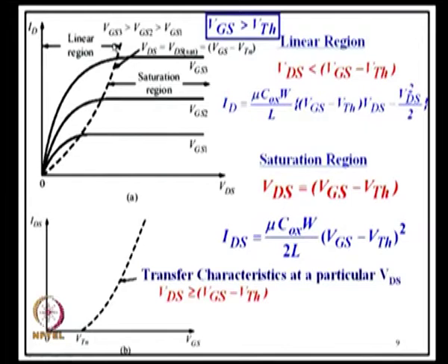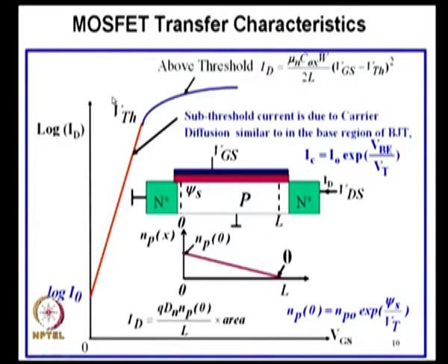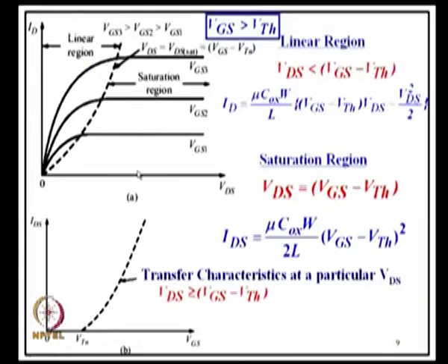And this is the curve which gives VDS is VGS minus V threshold, because larger the VGS, larger will be the saturation voltage, that is what is projected here. In fact, this also will tell you that maybe I will not discuss that aspect. You can connect the drain and the gate together and you can get that characteristics, two dimensional characteristics, connect drain and the gate. VD is equal to VGS practically. So, that is what I wanted to mention here.